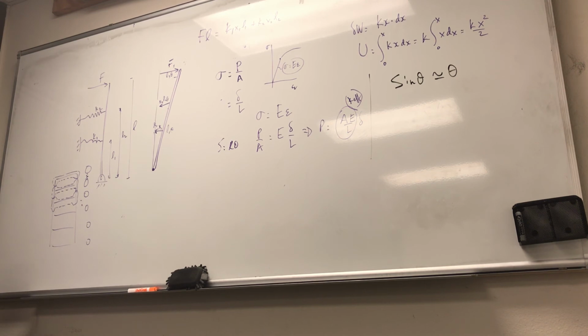In many practical situations, several masses appear in combination. For a simple analysis, we can replace these masses by a single equivalent mass by equating the kinetic energy of the three mass system to that of the equivalent mass, period. So what you're gonna say is, if I have three masses, for example, the kinetic energy of this mass plus the kinetic energy of that plus the kinetic energy of this guy is equal to the kinetic energy of the equivalent mass. In other words, it's 1/2 of m equivalent times the velocity squared, okay? Example here.